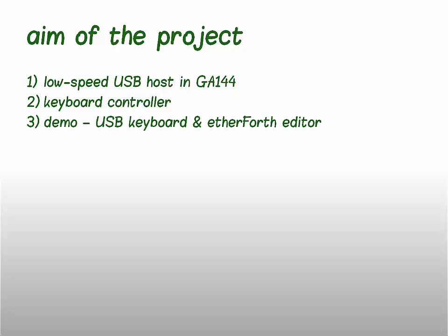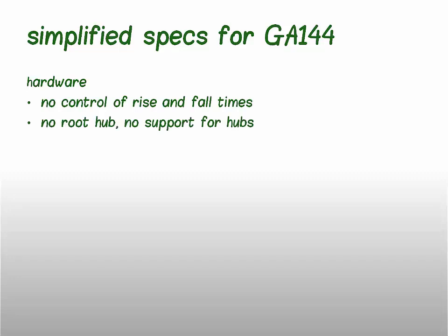Before we dive into details of the USB host implementation, we need to show how the specification has been simplified for this particular project. On the hardware side, we didn't employ any control of rise and fall times, and there's no root hub nor support for hubs. This may seem strange, as without hubs only one device can be connected to the host. However, for this project we don't need to connect anything else than just one keyboard, so the simplification is acceptable.